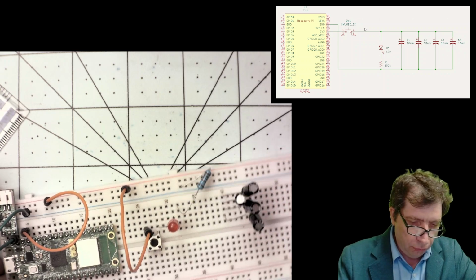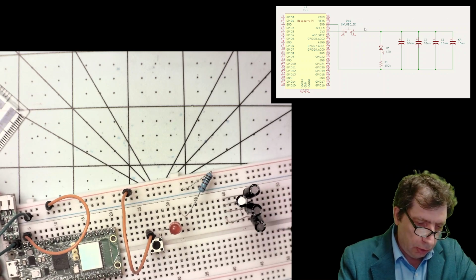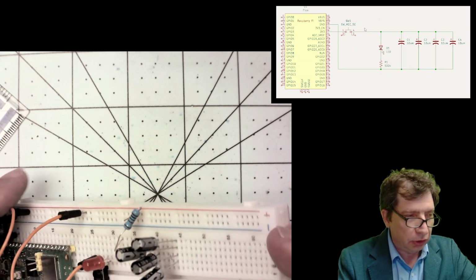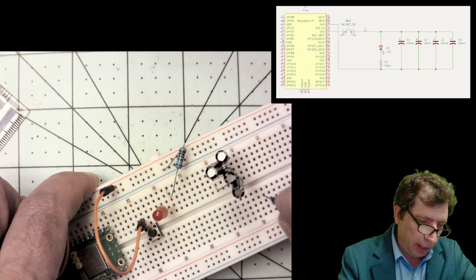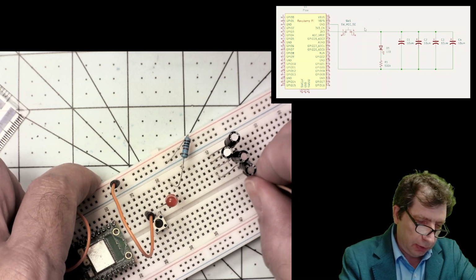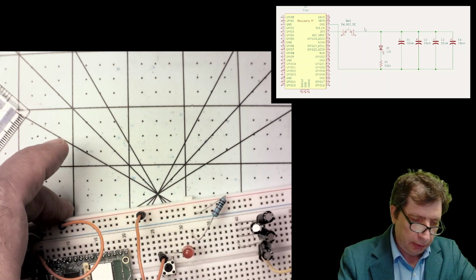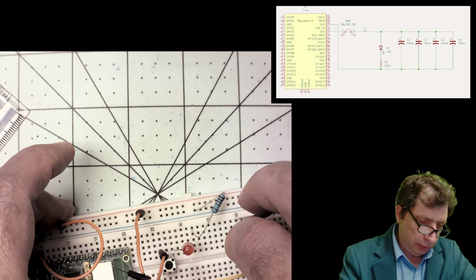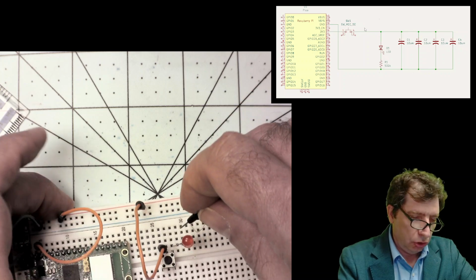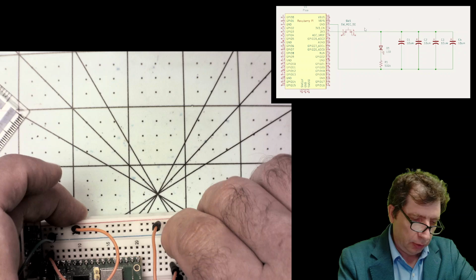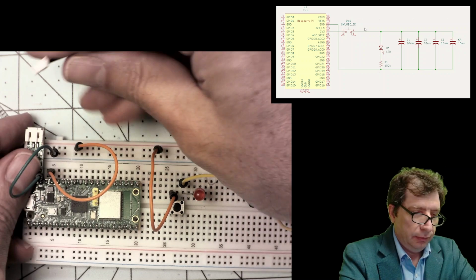So what we need to do, we need to connect them to the rest of the circuit. So the negative part of all those electrolytic capacitors is sitting on one wire. That negative must go to the ground, and positive must go to our switch, the same point. And it seems that everything is installed correctly.